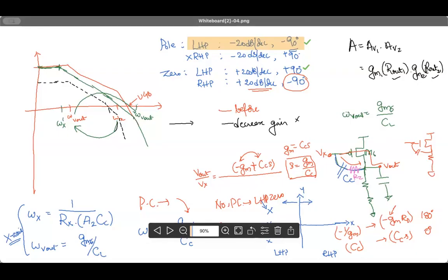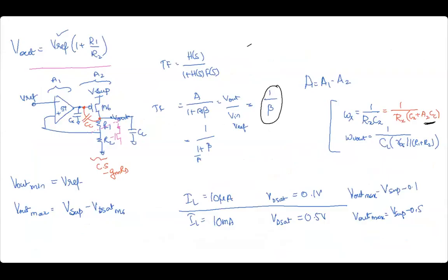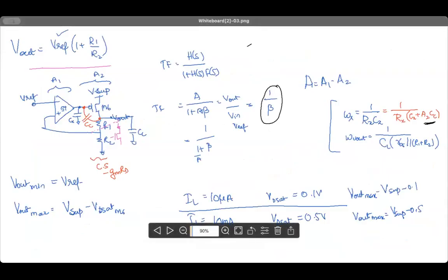It helps us to have a positive phase margin and hence stable. But it need not always be true. One thing here is that we are reducing the DC gain, and because the DC gain is reduced, the accuracy takes a hit. So you clearly saw that the A has to be as high as possible.